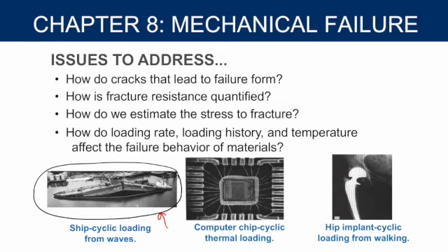So when it hit the iceberg and tore open part of the ship, it should have just tilted and the front of the ship should have filled with water, but they should have been able to continue moving the ship. But just the weight of the ship coming out of the ocean was enough to split the weakened metal because it transitioned to a different crystal structure. So it split in half and sunk to the bottom of the ocean.